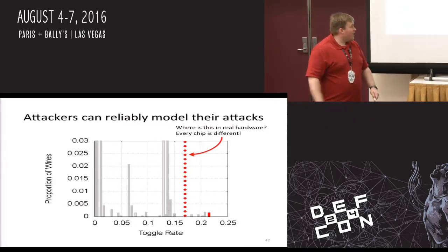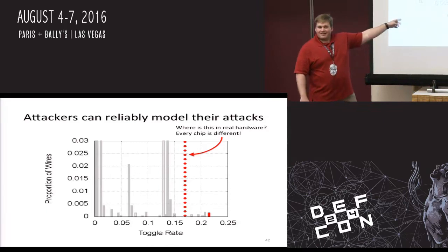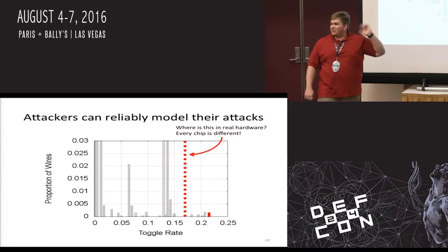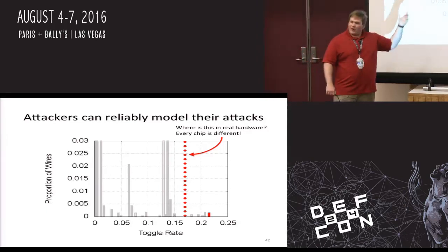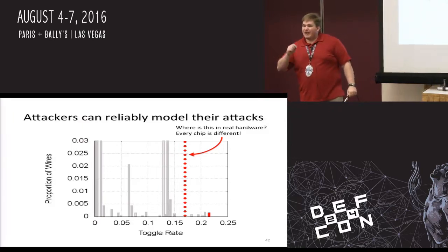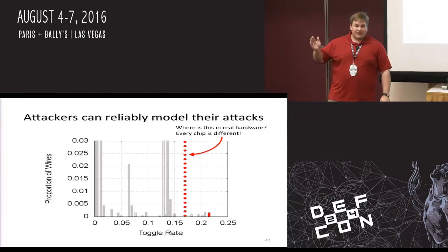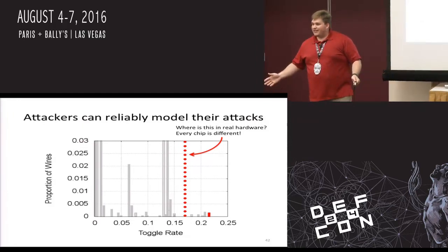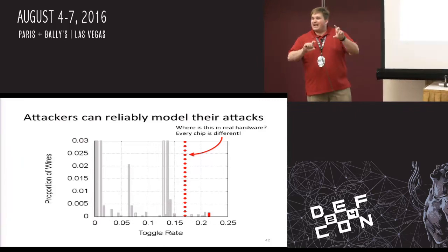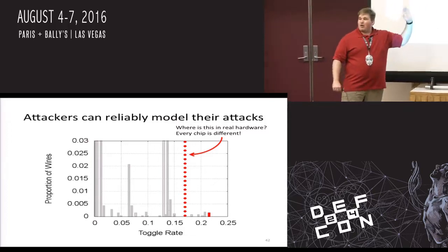Okay, so last little bit, I kind of lied to you about some of this stuff. This bar, I actually picked a random number where that was in previous slides. It's actually a question, where does that bar exist in real life? And those of you coming into the hardware space, every processor has a bar in a different location due to the manufacturing time variances. So you get a little bit more metal here, a little metal here. The capacitors are actually different ratios relative to each other. So that moves that bar around.